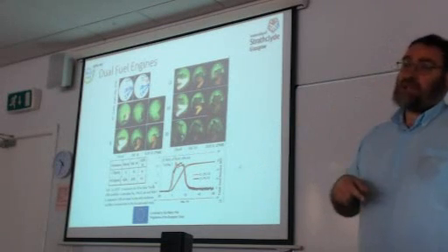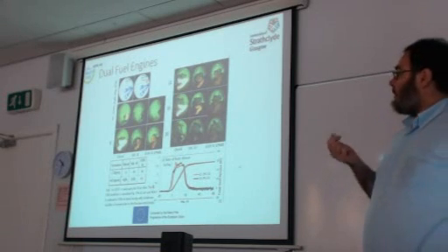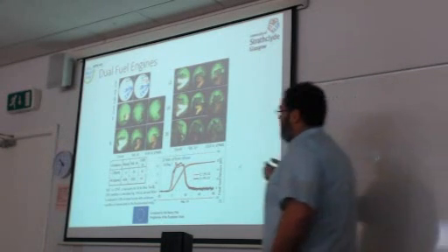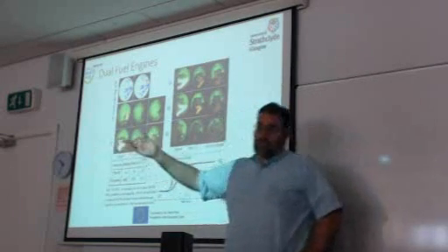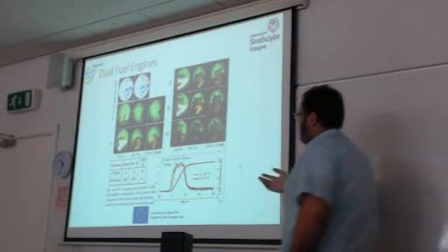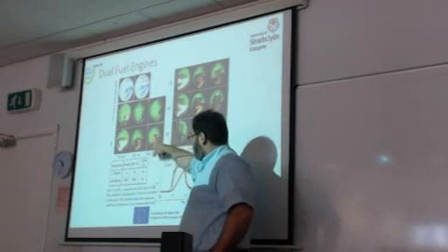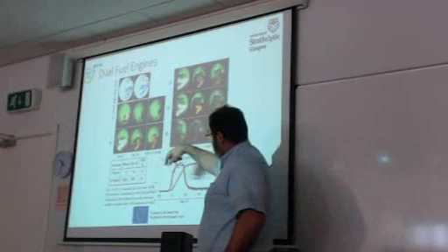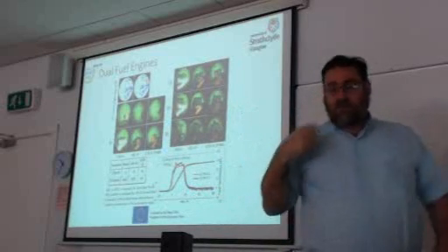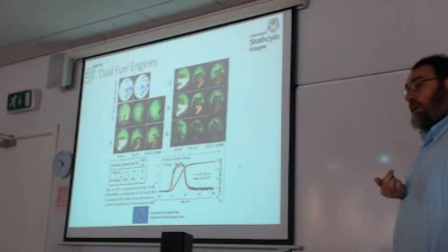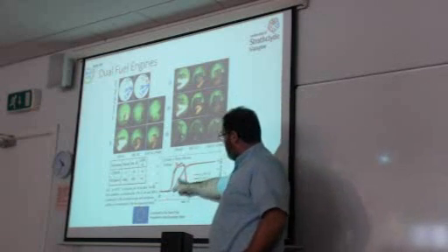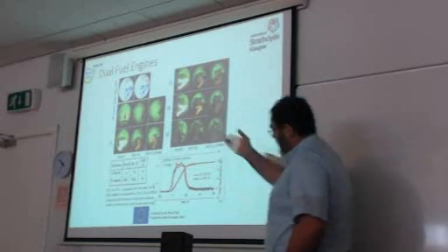So the EGR concept works that we take exhaust gas from the exhaust receiver of the engine, we clean it, we cool it, and then we provide this exhaust gas to the scavenging receiver. And by doing that, the oxygen level is decreased. So instead of having an oxygen of 21%, this is the oxygen level condensed there, 21%. Then with EGR we can reduce oxygen level, and in this case, in these frames here, we have a case with oxygen level 17% instead of 21.